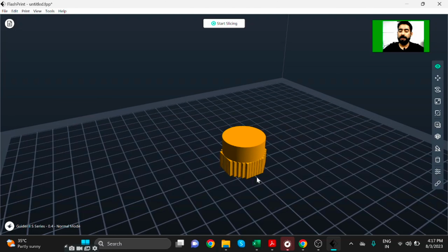But by placing the supports, we have three major disadvantages. One of them is that this support material is an extra material, that is, it is a wastage of material, because once the part is completed, you have to remove these support structures. Second, this support material deposition also takes time, so the overall build time of the part increases. And the third disadvantage is that wherever these supports are placed, it damages the surface of the part and makes it rough.